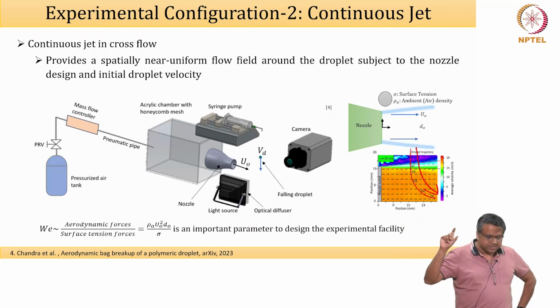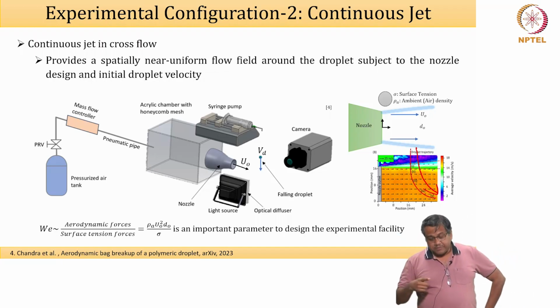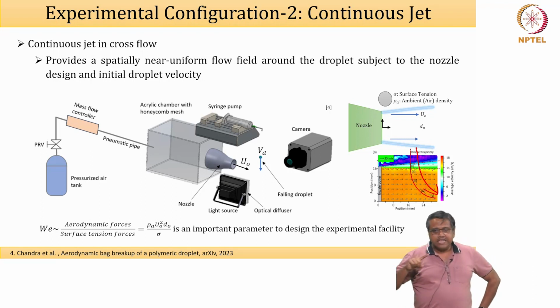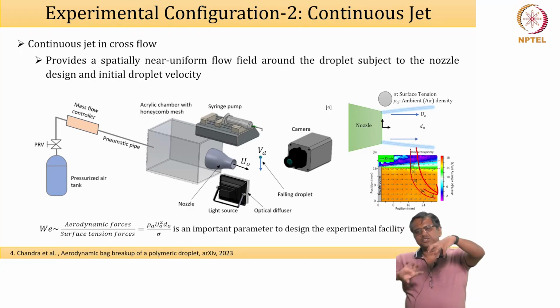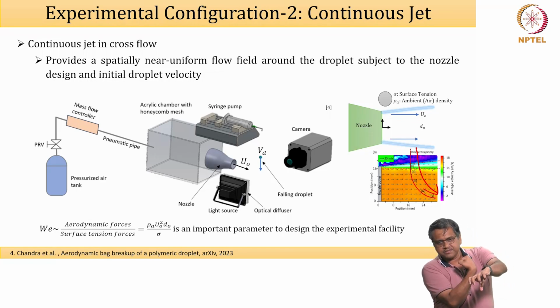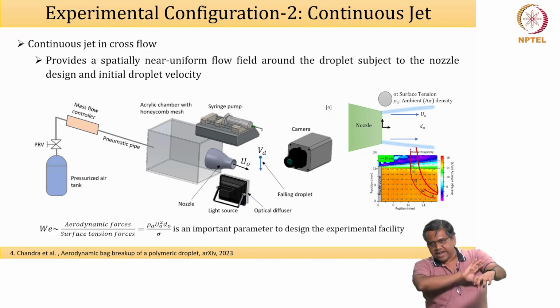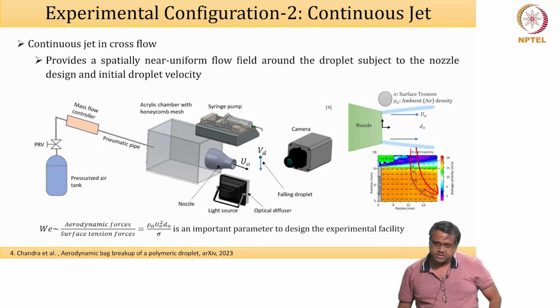It is not just the aerodynamic forces, in most cases it is. Okay, in cases, especially with applications which involve turbulence, it can also involve the circulation based Weber number. That means, for example, this is a droplet, especially in secondary atomization, you will find that there is a vortex which rolls it up. By Weber number, we naturally mean the inertial forces which are rather nice. But if you have a vortex which is squeezing the whole thing, then it is a vortex based Weber number, or basically a fluctuating Weber number, which becomes rather important.